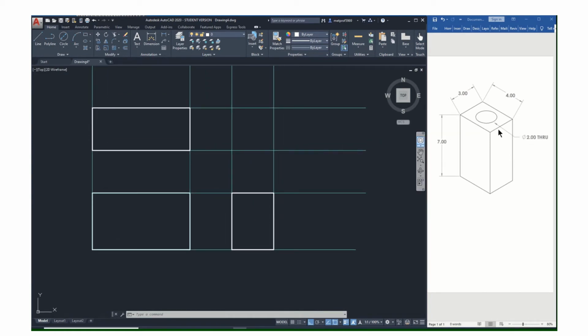So we've got this hole, it's a 2-inch diameter hole, goes all the way through the part. Now it's located centrally. I know there's some dimensions missing on there. So in order to locate that, since that's 4 inches, I could just do an offset of 2. Oops. And then that's 3 inches, so that's going to be offset of 1.5, just half of that. So I know that my hole is going to go right there. Make sure you're on center, comma, diameter, and that's 2 inches.